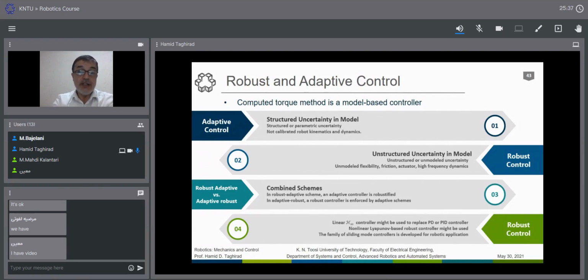But if it is AC, and we have a high frequency voltage applied, then this simple resistance shows some inductive properties. And if you increase the frequency, this inductance parameter, which might be very small, becomes more visible. And you can see that this is not a simple resistance, it has an inductive part and a resistive part.